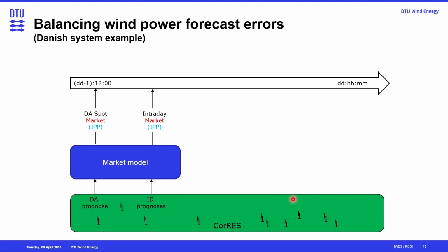But with a larger share of renewables coming in, now this is also an opportunity for the independent power producers to say that, yeah, 1 day before I had this much forecast error, but now my forecast error has improved. And this is still debatable, whether it's useful to act 6 hours before or 12 hours before, because it is also driven by the forecast models.